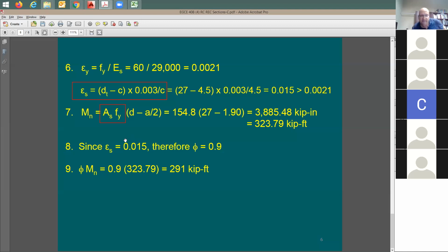Also, the size of the concrete section was given, and the material properties were given to you. What is a material property? For example, I said concrete strength is going to be 4,000 psi, or 5,000, or 3,000. So I gave this to you. Also, I told you the steel is going to be grade 60, which means yield is going to be at 60 ksi.